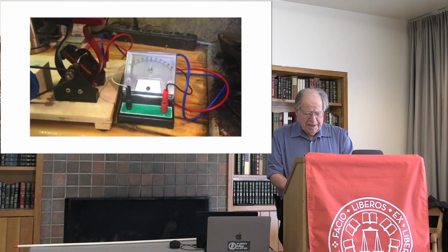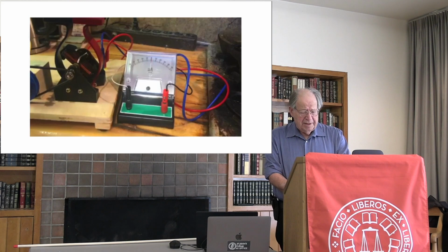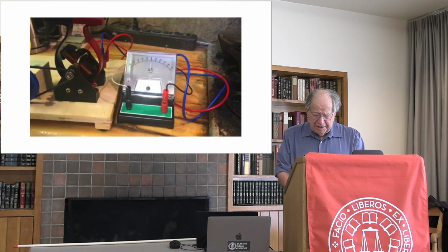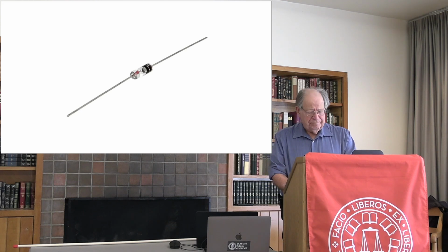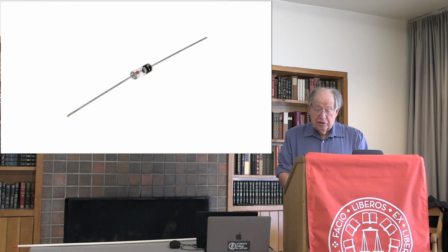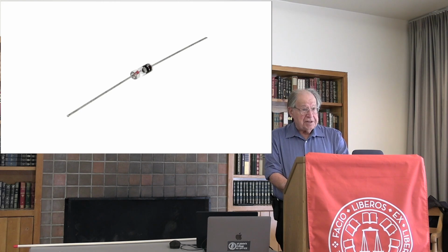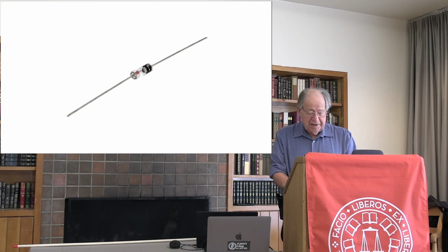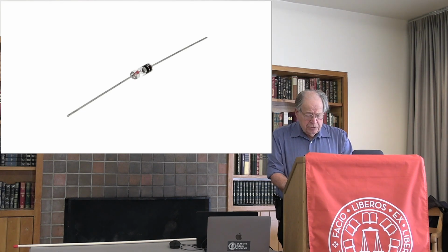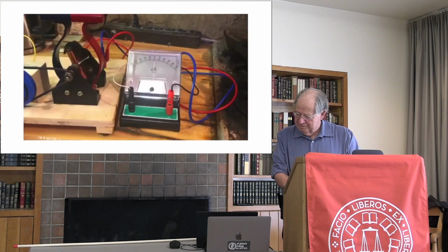There are a number of ways to adapt DC ammeters and voltmeters to measure alternating current. The simplest method uses the rectifying diode pictured here. This device conducts in only one direction, so the meter, instead of being exposed to successively reversing pulses of current, receives only those pulses having the chosen direction, and accordingly registers in one direction only, like this.